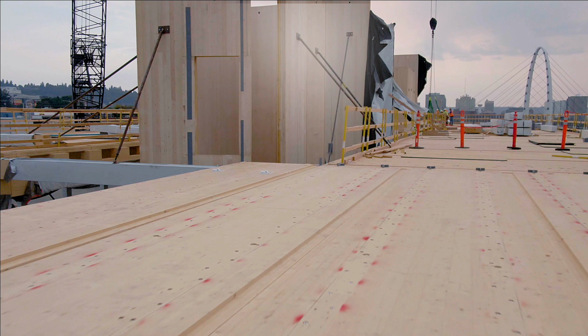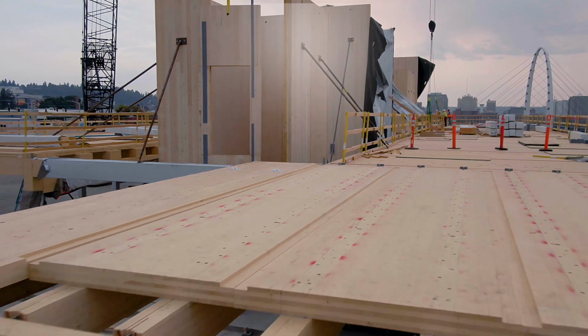And as you can see here, I mentioned before that there was glue laminated beams. Well, this also has a CLT lift core. These stair cores in the center of the catalyst building are also CLT. Generally, you find that that's often concrete because regulations in locations like the US and Australia and Europe often don't allow that to happen unless there's a really good fire suppressing system and a building regulatory certifier that's comfortable with having CLT or mass timber cores.